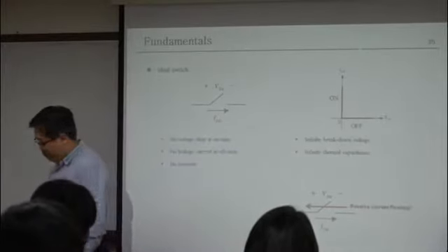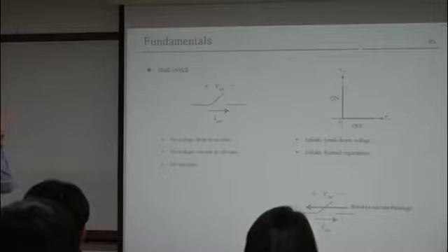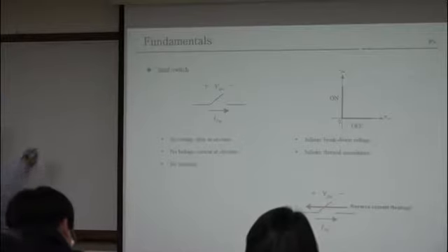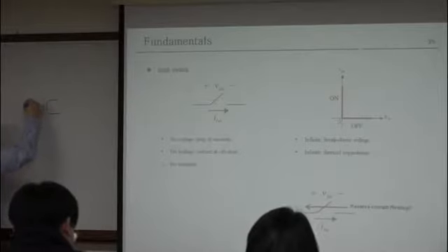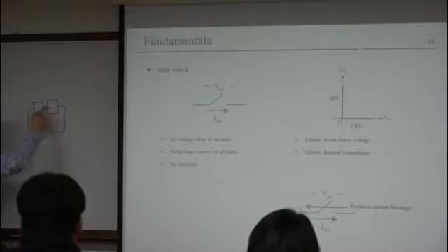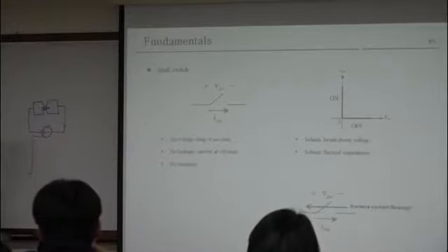What does it mean? Okay, there are mainly two reasons for failure of a power semiconductor. The first one is the isolation. The second one is the thermal. What does it mean? If you have two conductors here and you apply a voltage, then if you increase this voltage very high, the current can flow through the air, right? In that case, your semiconductor fails, right?